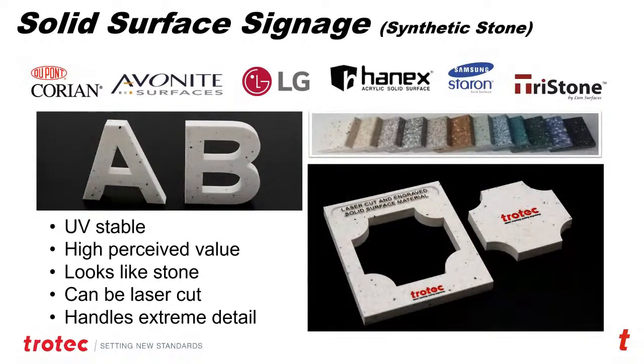But the one thing most people don't understand and know is that solid surface or synthetic stone type materials are laser friendly. They can be cut and they can be engraved with unbelievable detail. And so I like to use this stuff for making signage because it's a very stable type material. It's made from an acrylic base and bauxite. Bauxite is the same material that's typically smelted to make aluminum, believe it or not. And so when you're cutting and engraving, the residue and smoke and stuff can be a bit abrasive on your laser machine. And so you want to make sure you keep your machine clean if you're going to do this a lot. But the finished result is stunning.